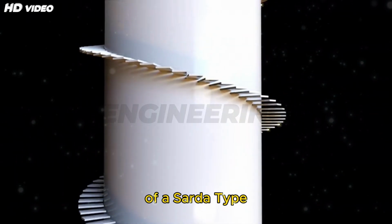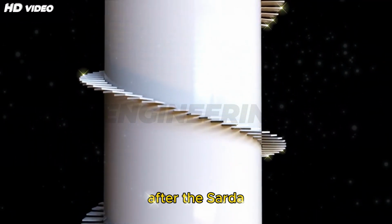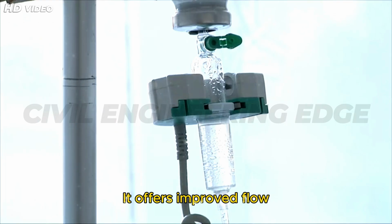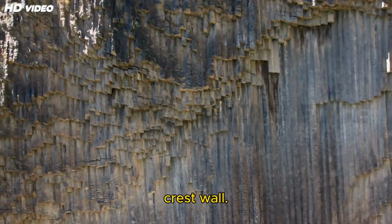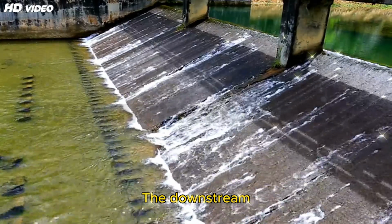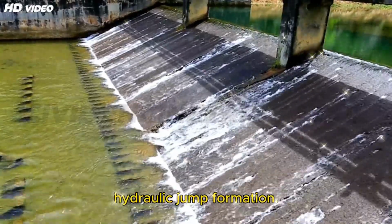Segment 7. Design of a Sarda-type fall. The Sarda-type fall is named after the Sarda canal system and is suitable for discharges up to 14 cubic meters per second. It offers improved flow regulation and energy dissipation over the simple drop fall. Structure: the Sarda fall has trapezoidal notches in a raised crest wall. The flow passes through these notches, and the remaining width carries water at normal depth. The downstream glacis with a masonry or concrete apron allows hydraulic jump formation.